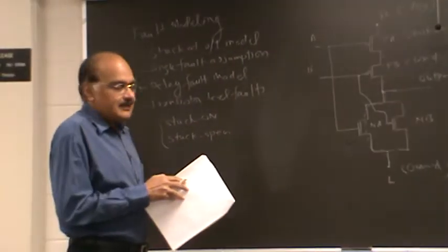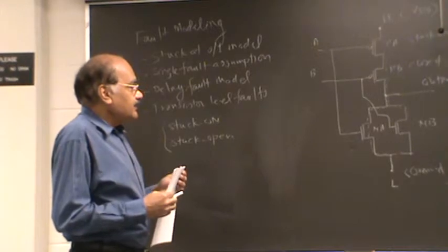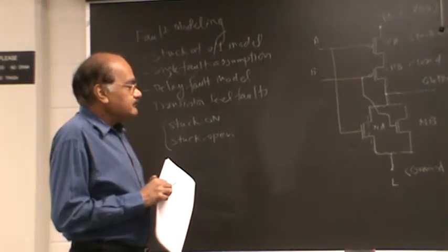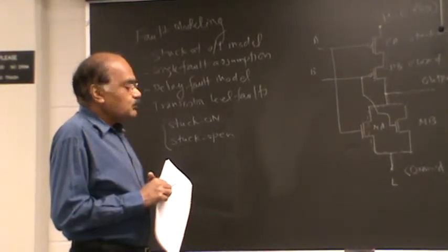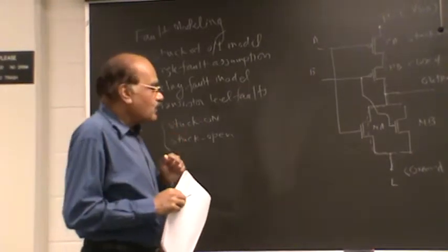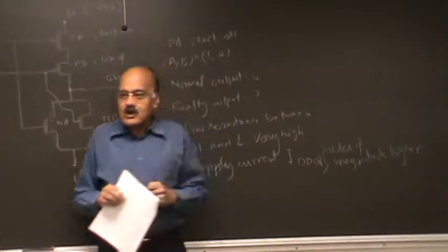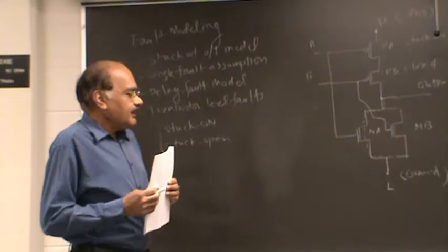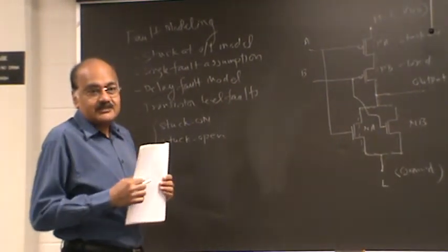So if you are monitoring the supply current, then this type of fault is easy to detect, provided the normal supply current in the circuit is not too high. Now this could be a difficulty in very large circuits where ordinarily the supply current is very high.